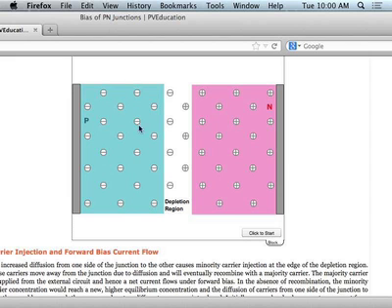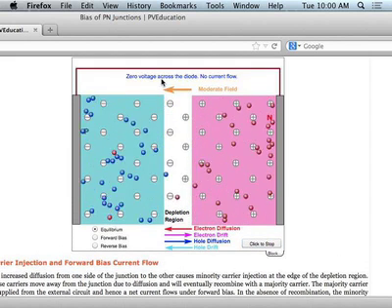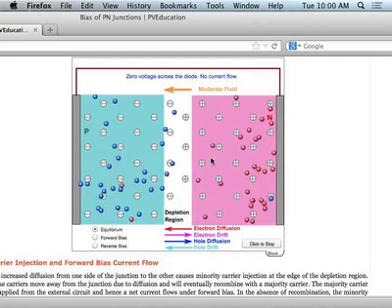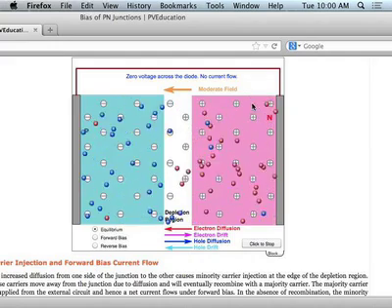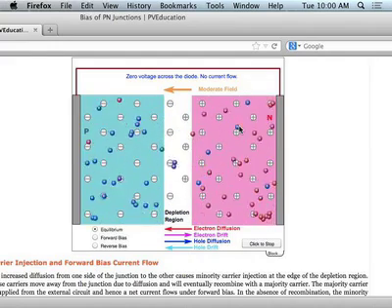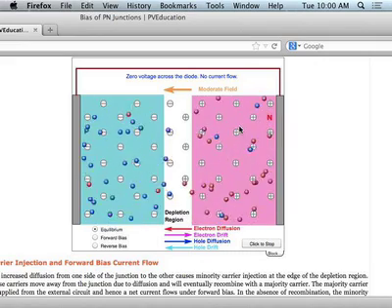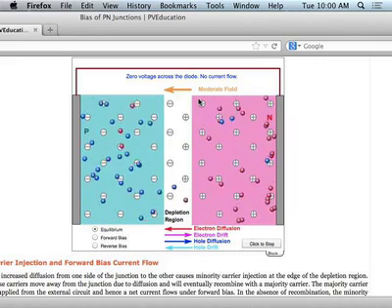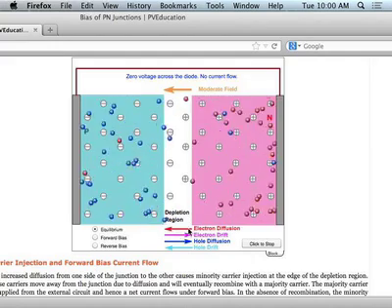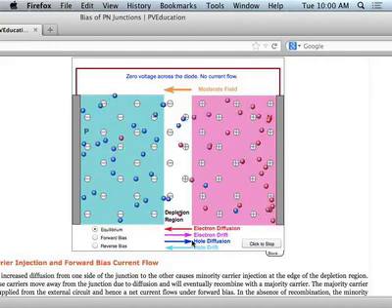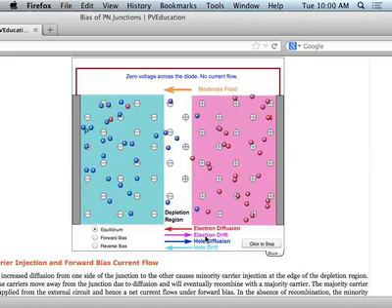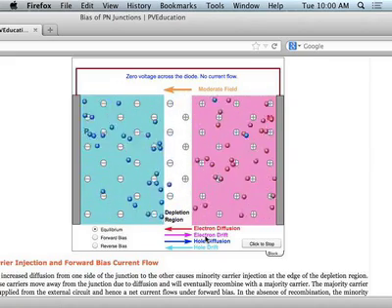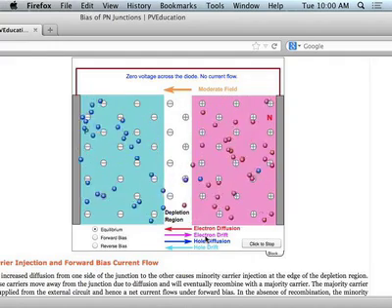So you can see P-type, N-type, depletion region, okay, and they're going to apply a voltage. So in this case, it's equilibrium. Not many carriers cross, okay? So holes come in here, they get swept back. The electron comes in here, they get swept back. Those are the majority carriers, okay? Overall, the current is canceled. There's a moderate field here which balances the current. So you can see the electron diffusion goes this way, hole diffusion goes the other way, electron drift goes this way, and these two have to cancel, and these two have to cancel. This is what we saw before. So this is the picture I want you to keep in mind. So make sure you go back and think about this, look at it.